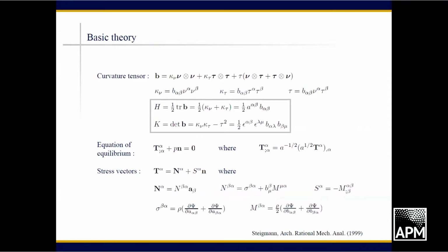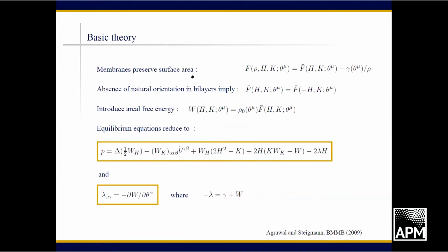shell theory. What is interesting about our shell here is that it's essentially a liquid shell. One can show either by a dimension reduction procedure from three-dimensional liquid crystal theory, or perhaps more appropriately from material symmetry arguments for the actual shell itself regarded as a two-dimensional continuum, that the dependence of the energy, I'll call it F here, on the curvature is via the mean and Gaussian curvatures, and also possibly a density, a mass per unit area in the surface.